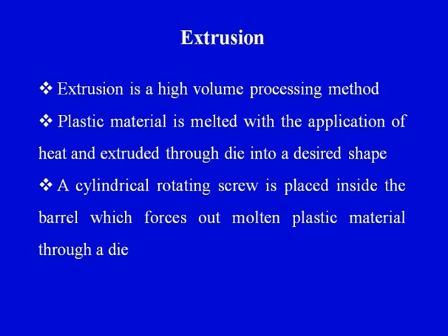Now, depending upon the length or the size of the final product required, we may have a cutting arrangement which may be automatically cutting the final product into the desired lengths. So, the extrusion process is a high volume processing method, production rates are very high. Plastic material is melted with the application of heat and extruded through the die into the desired shape.